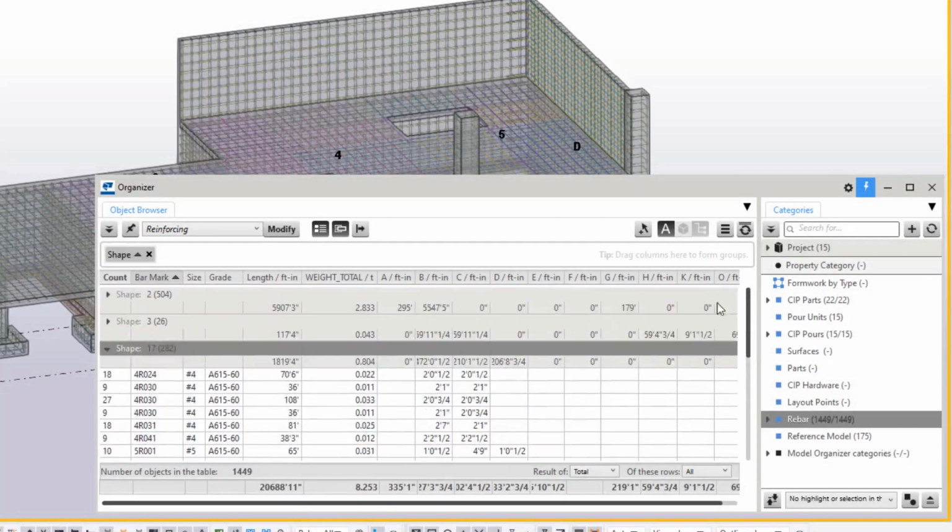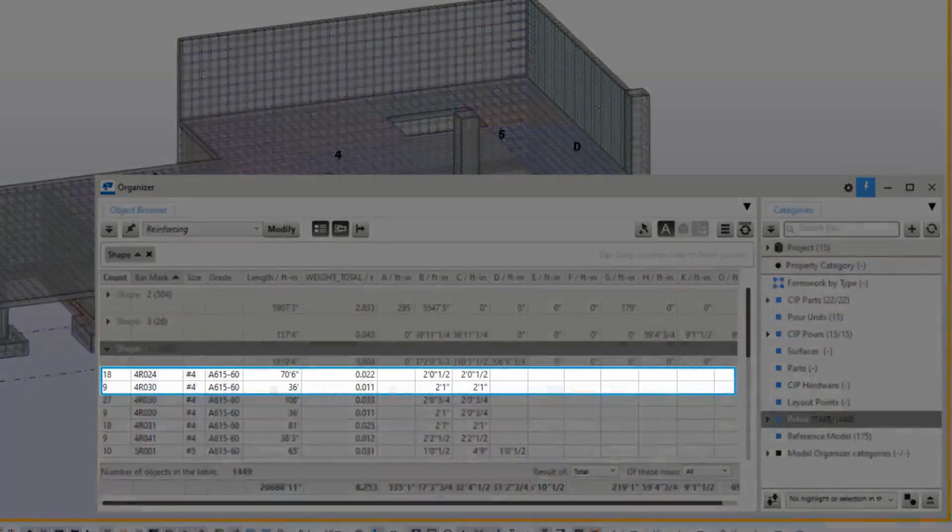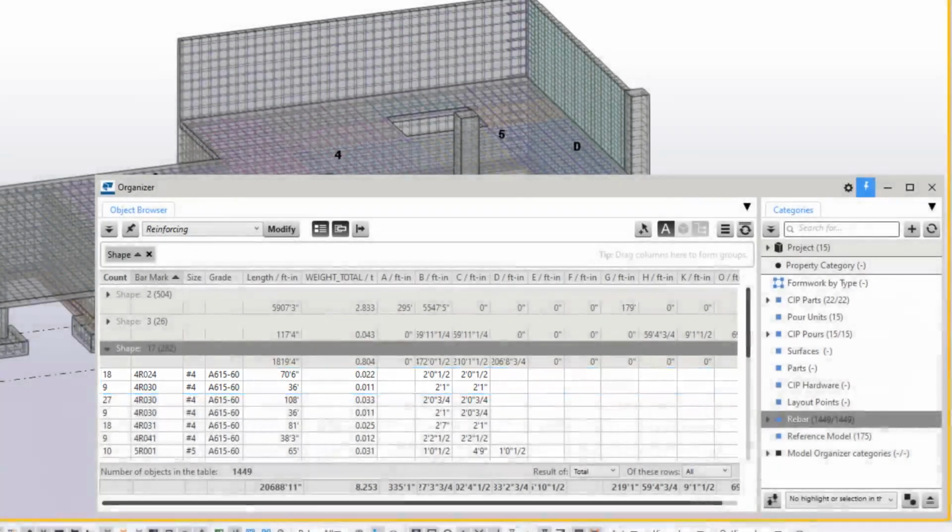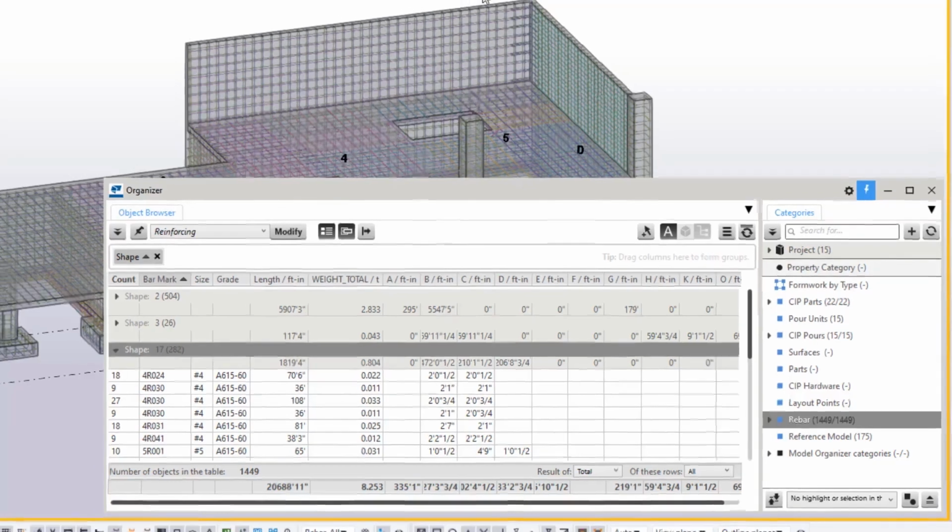Here, we can review and filter out our bending schedule and see if there are any adjustments that need to be made. For example, bars that are very close in dimension to one another. As we can see, it's easy to identify that we have some number 17 bars that are within 1/2 inch of each other on the outside leg. This may be necessary, but also may not.